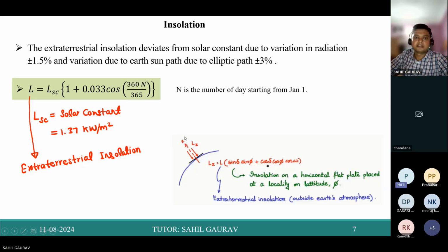In the series connection of the solar PV panels, we were introducing a diode so that whenever there is a mismatch between the ISC and VOC, the diode will short circuit and negative power will not come into the picture, sir. Am I right? When you have not put this protection diode, then this negative power will come.